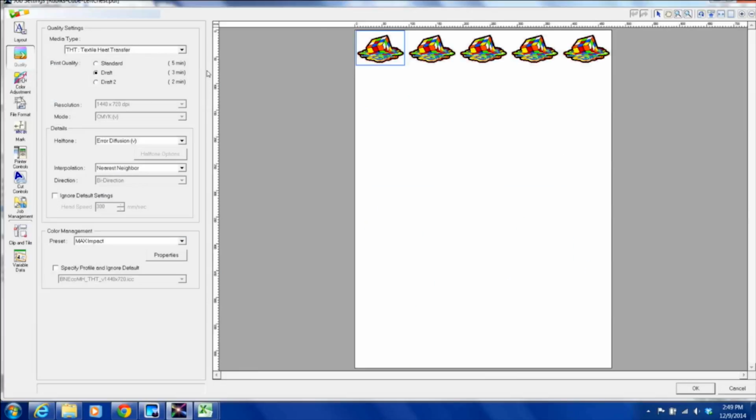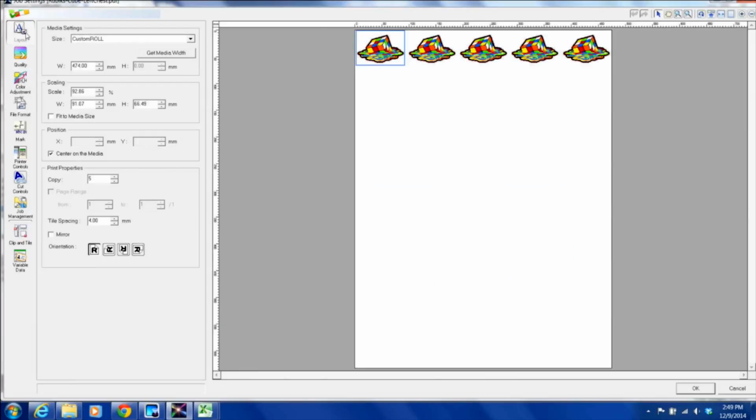And this, for your benefit, is about how long it takes to set up a job outside of Corel and Illustrator. Again, when you dig into Corel and Illustrator for the print cut process, you need to send a graphic with a vector line around it. Now, anything inside of that vector line can be a bitmap, just like your direct-to-garment printing, but you do have to have a hard edge, which you'll see as we go through the print, cut, and weeding process. You won't be able to get feathered edges or see your design fade into the garment with print and cut.